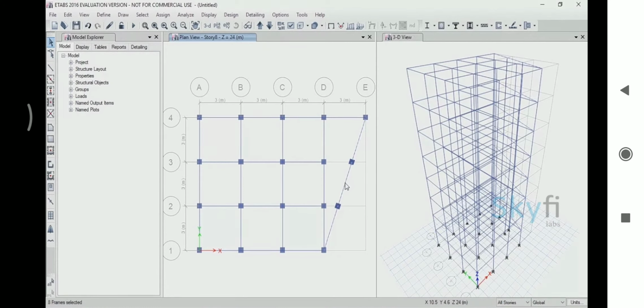Now that all the columns are placed, you can draw the remaining beams. Kindly note that the inclined beam that you had drawn was one single beam. But actually, these should be 3 separate beams, 1 beam between each pair of columns. You had drawn a single beam only to help you in locating the reference point. Select the single inclined beam, and delete it.